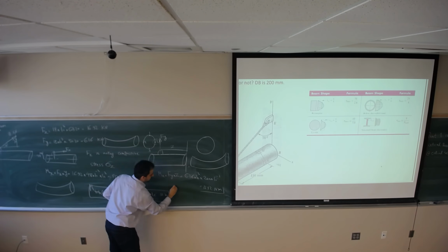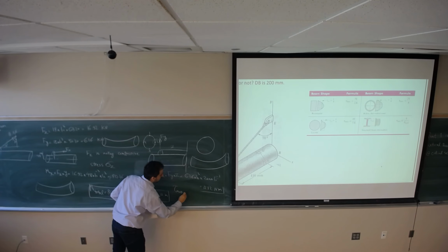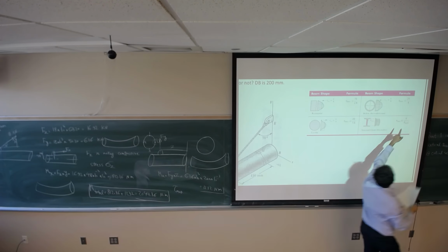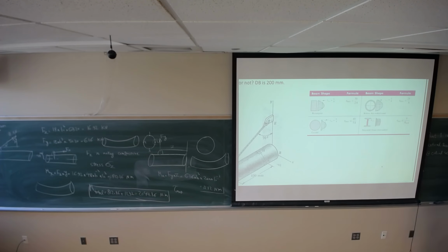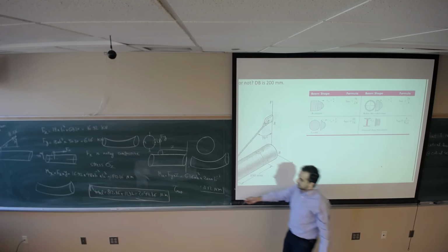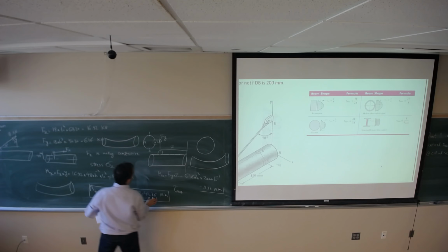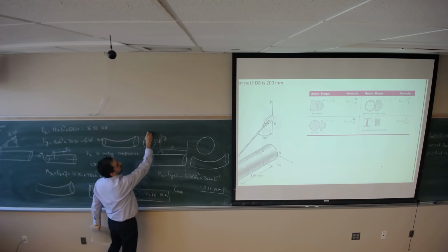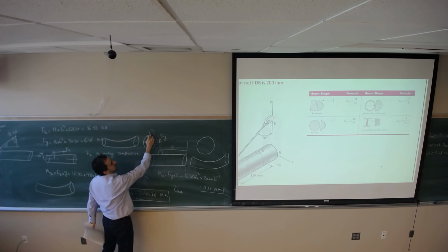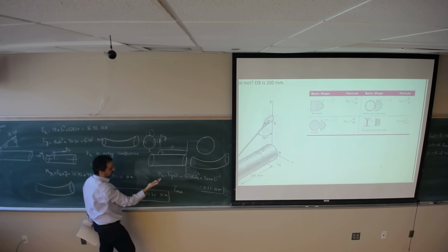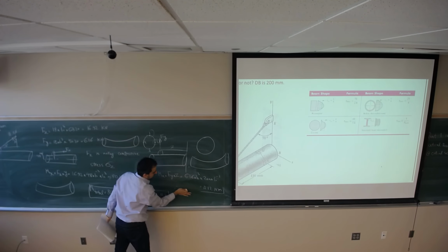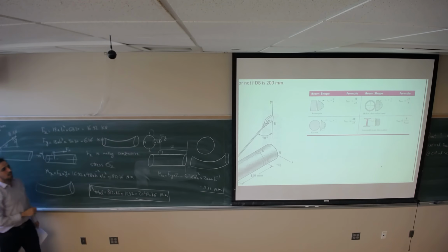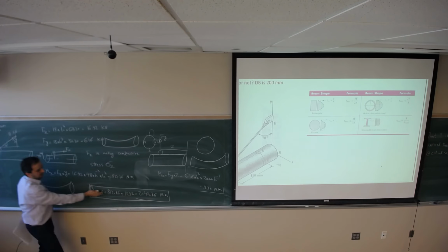We should find the tau max at point 2, which is gonna be the force times 2 divided by the area, and compare it with the normal stress that we get from this bending moment and this compressive load, which makes the normal stress at point 1, and then compare these two. But typically, the tau max coming from the transverse shear is a very small number compared to the bending moment stress.